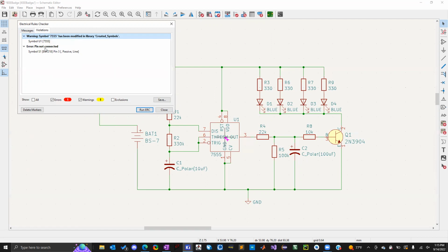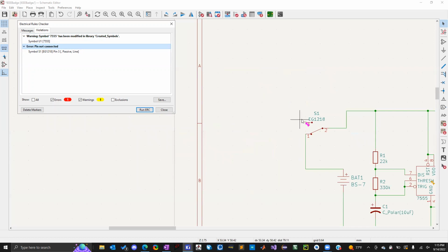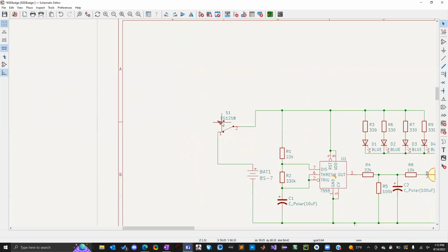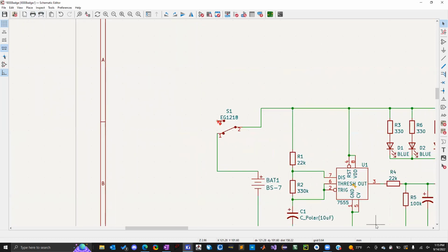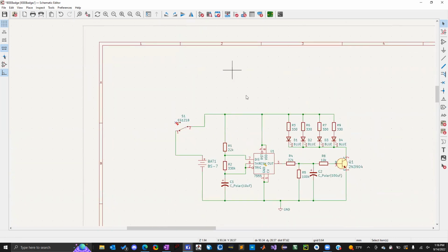And then it also has a warning here that there's no pin connected here. So that can be a problem when you move into the layout. The easy way to fix this is on the right here, add a no connection flag, and then you would just click on that side. There's no connection there because that's effectively just going to be our off and turning the circuit off.